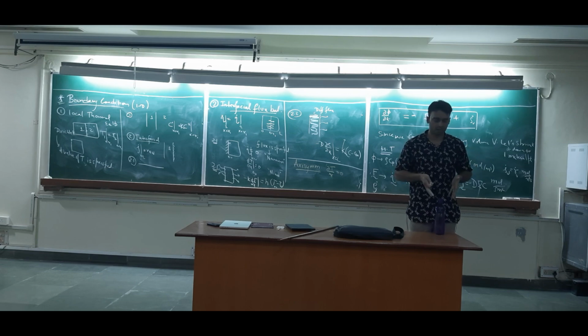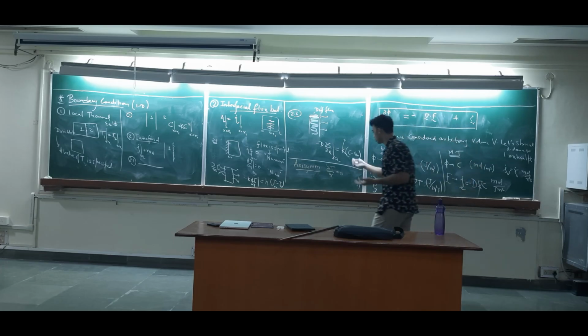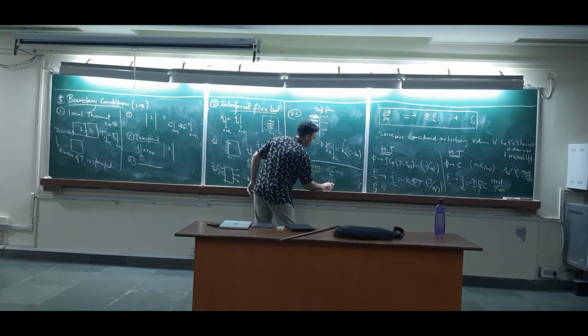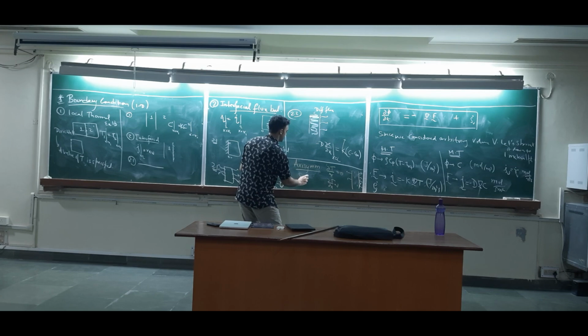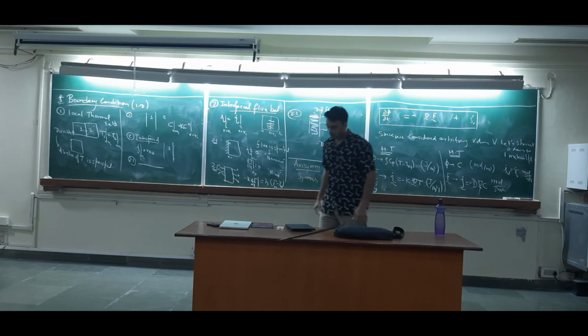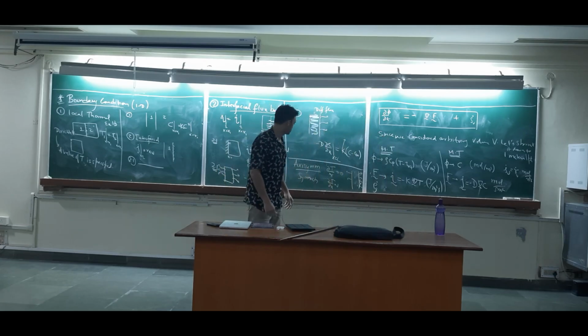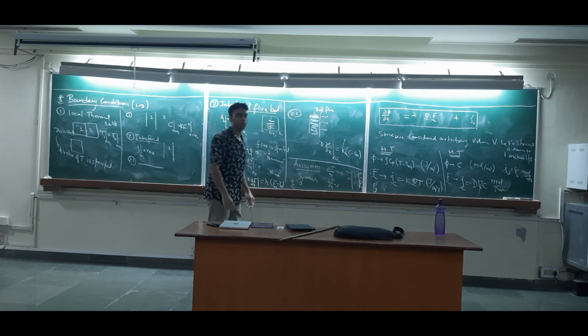If you have a slab, and it's heating both sides uniformly and leaving the heat flux outside through convection, at x equal to 0, the center plane, you will have dou T by dou X equal to 0, right? So you could have dou T by dou R or dou T by dou X equal to 0 for symmetric problems like this. That would be called symmetry. For cylindrical, it will be known as axisymmetry. Basically meaning Q dot is 0, J dot is 0, flux is 0.